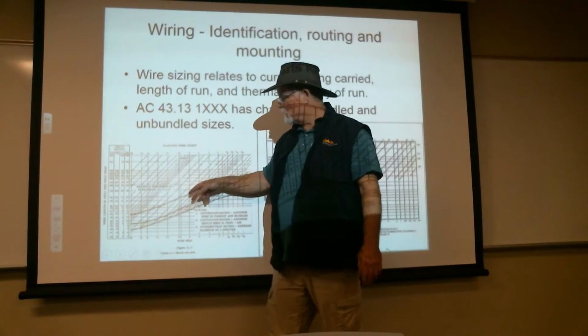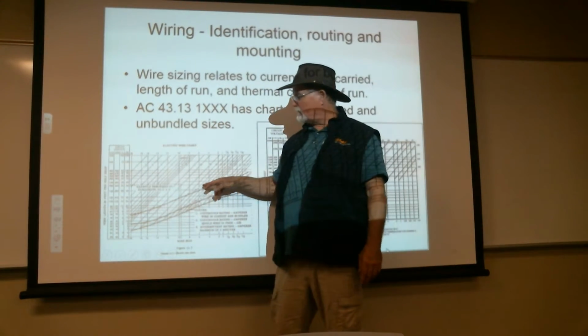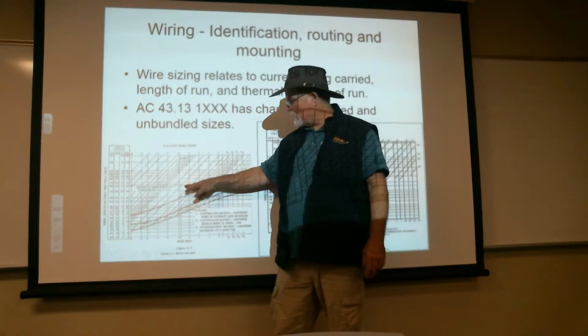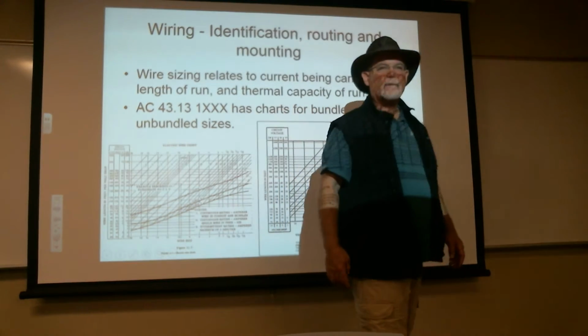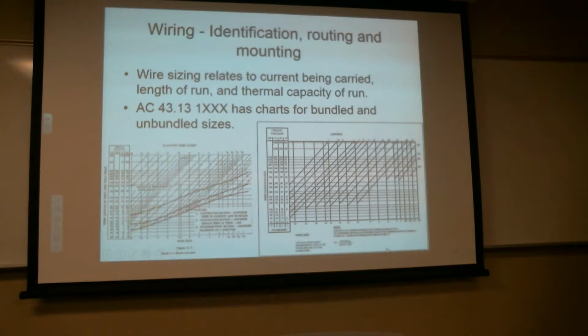So you've gone out to here, voltage or length, based on the correct voltage chart, out to current, then drop down or up, either way. I'm sorry, I meant to say, is it copper or aluminum, how do you know? There's only really about 4 applications I know where they use aluminum wire. So it's all going to be copper wire for these. It doesn't say it, but yes. Essentially, if you can get away with just using that chart, you would then use it.